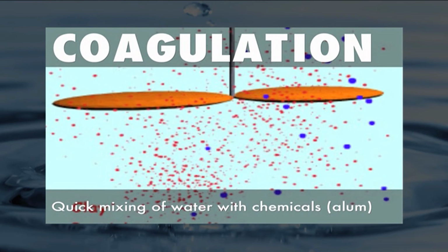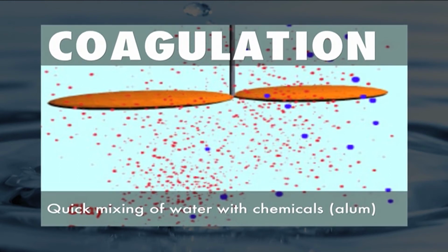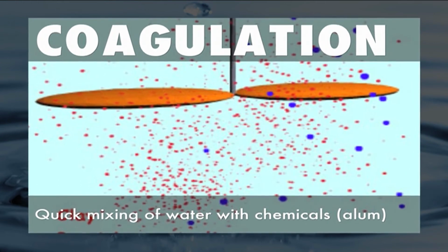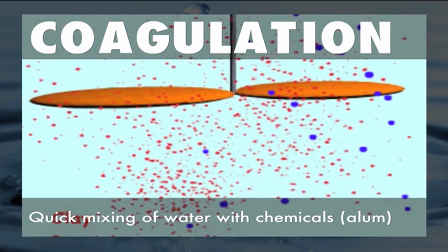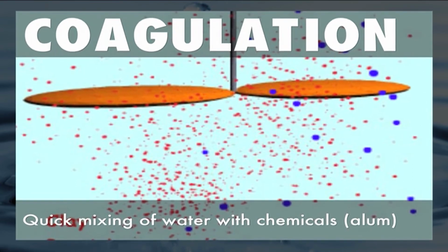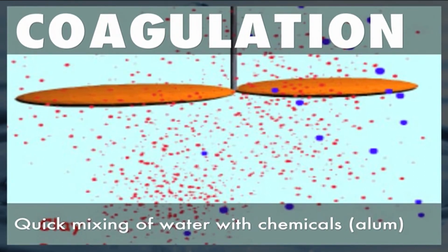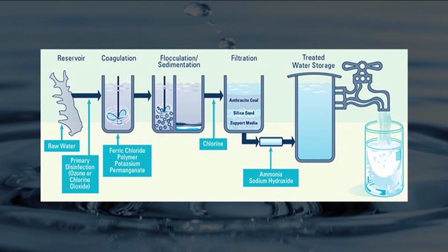Fine particles do not settle and are thus required to be removed in the next step, coagulation. Fine particles and colloidal suspension are combined into large particles by a process called coagulation. This step is carried out by the addition of special chemicals called coagulants or flocculants such as potash alum. The large particles either settle to the bottom or are removed in the next step, filtration. Suspended particles, flocculants, bacteria and other organisms are filtered by passing the water through a bed of sand or finely divided coal or through some fibrous materials.